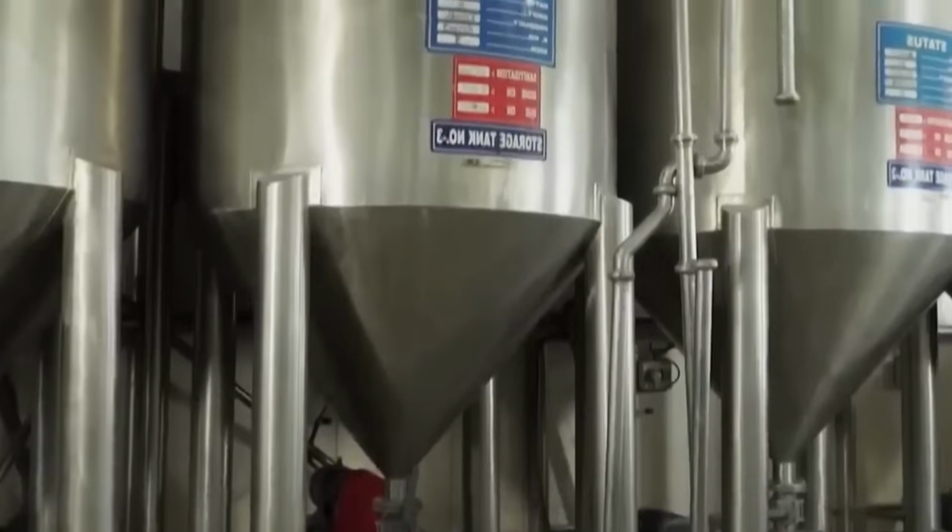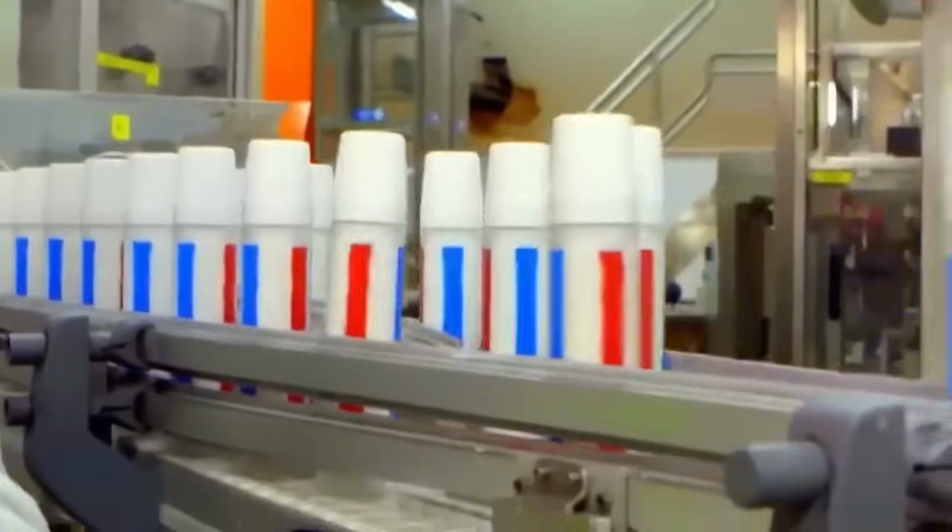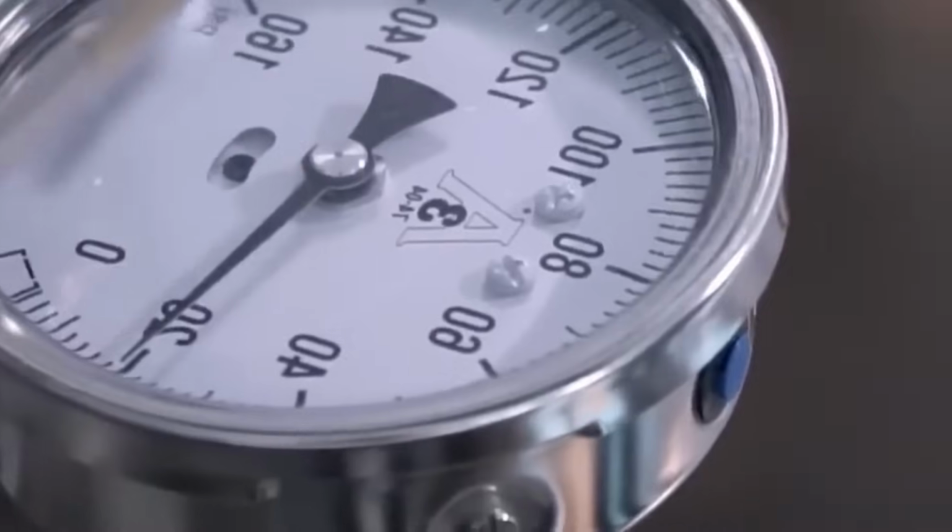Tubes are fed one by one into indexing star wheels that position each unit beneath the filling nozzle. Optical sensors ensure correct alignment based on pre-printed registration marks. Filling nozzles are submerged slightly into each tube and retract upward during discharge to prevent air pockets.